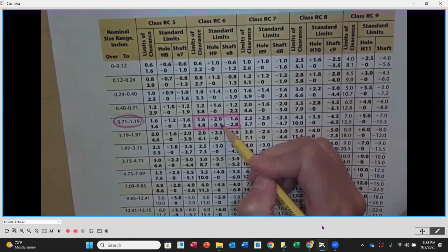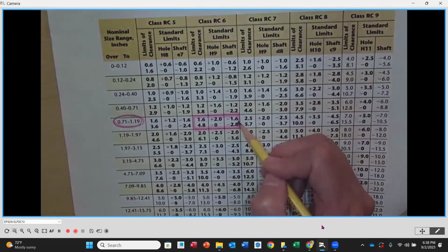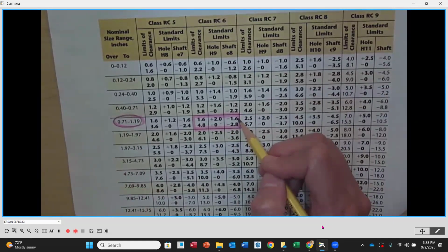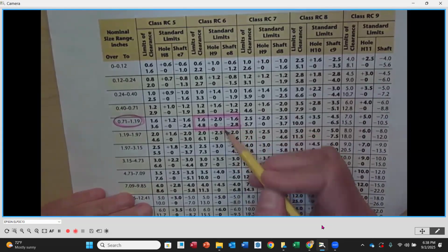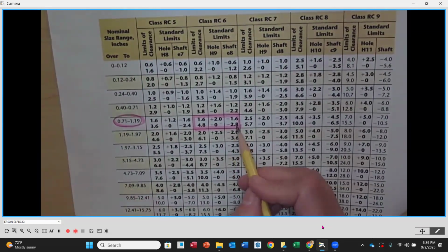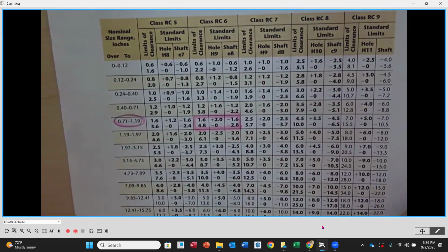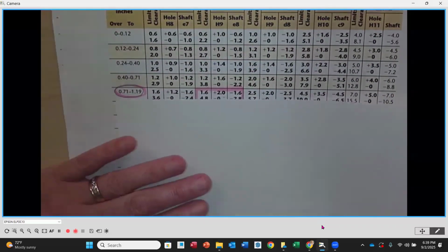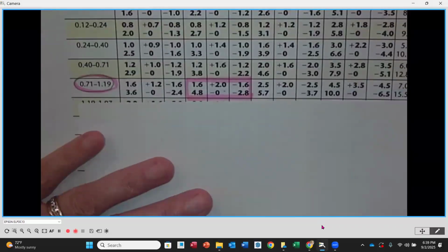That sounds familiar. Remember, that's going to be the size of the drill, the nominal size in our hole size. Then on the shaft, we're going to take that same 0.75, but we're going to subtract 0.0016. So again, 1, 2, 3 to the left. So that's going to be 0.0016. And then we're also going to subtract for the lowest limit on the shaft 0.0028. I know they have it written out there, but I think it's worth showing you how this works and showing the numbers.